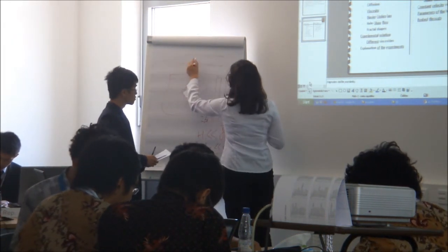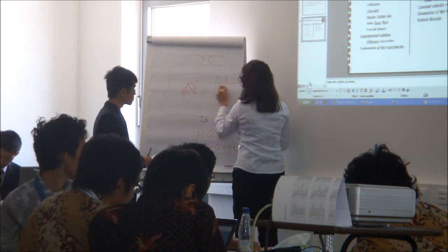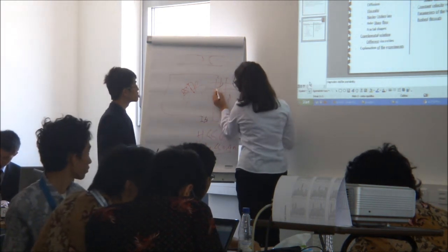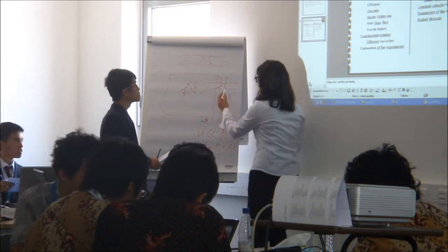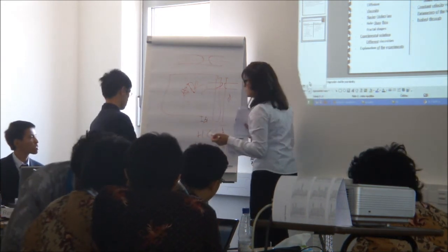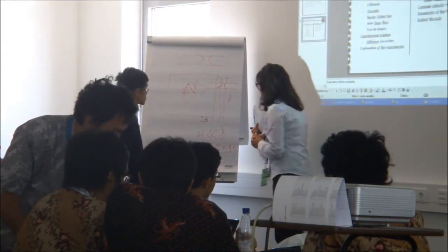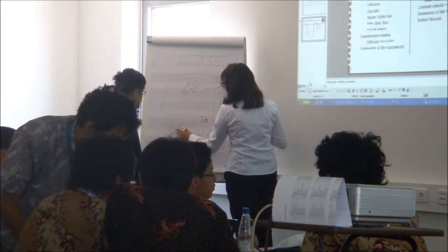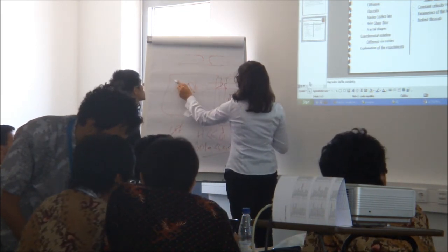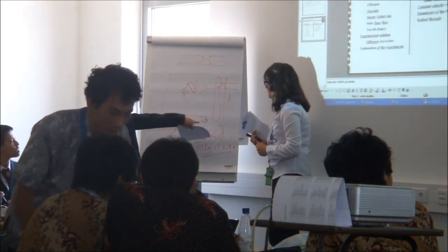This is because when we have the meniscus shape, we can approximate this to a symmetrical one. But when we have a very big separation, the menisci will be like this. So we cannot make the same approximation, and we will have a different mathematical model for it. So we could not approximate it to a Hele-Shaw flow. When you have 6 and more millimeters, the velocity is different. It has a different behavior, not the linear one.